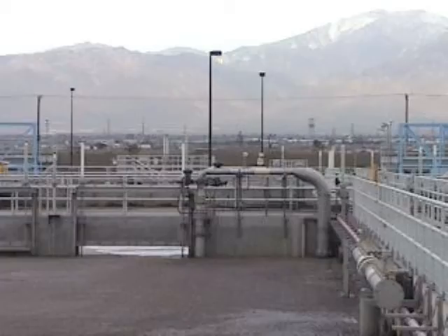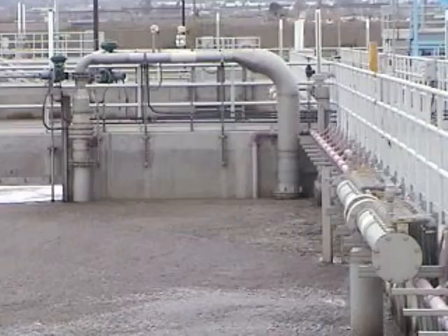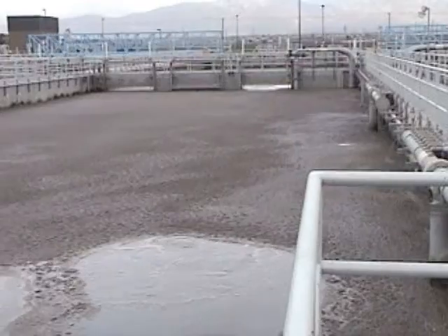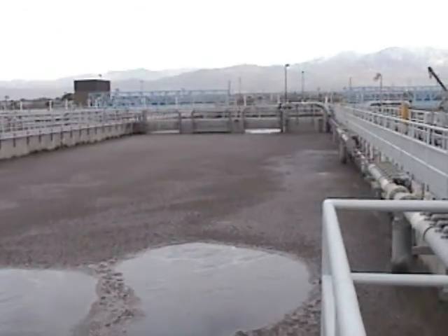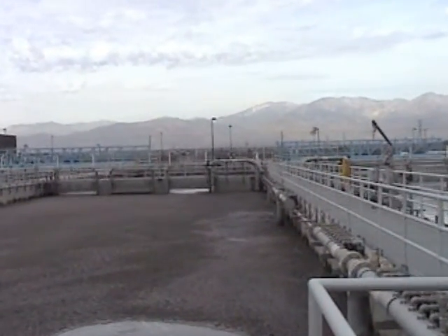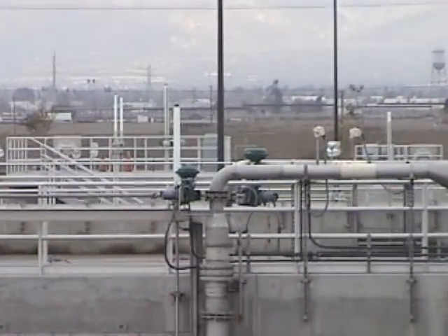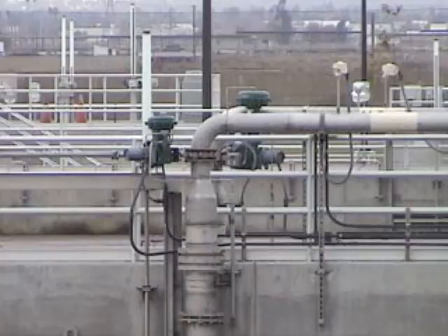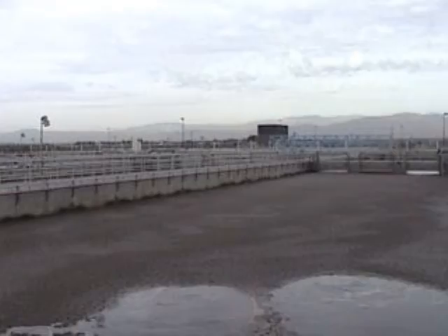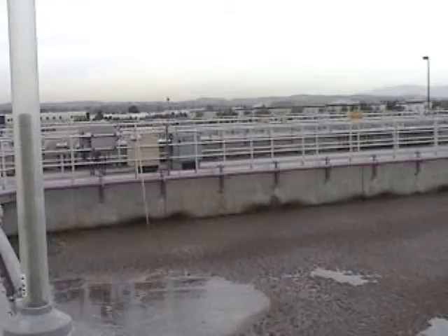With the valves open at 100%, if you're looking at the SCADA system and you see that your set points are not being met, what you want to do is bring up the valve graphic and take a look at the valves. If they're 100% open and you're still not meeting your DO set point, you want to have the instrumentation guys take a look at the DO probe and make sure that the probe's really telling you what's really happening. If the DO probe is right and the valves are 100% open, you want to take a look at the blower and see, is it producing enough air?